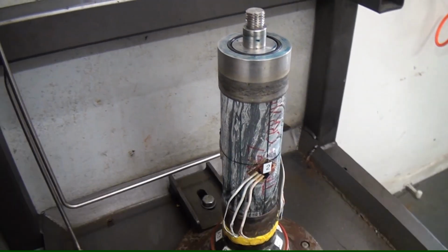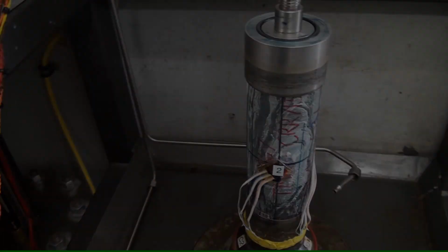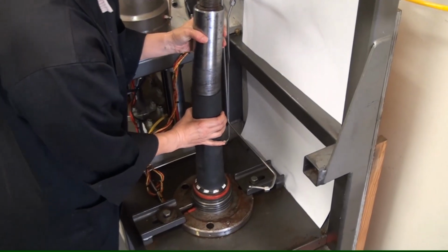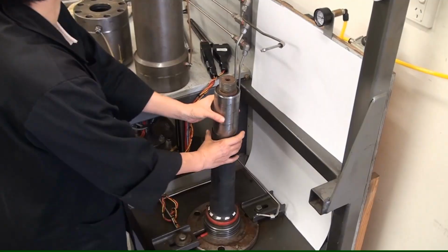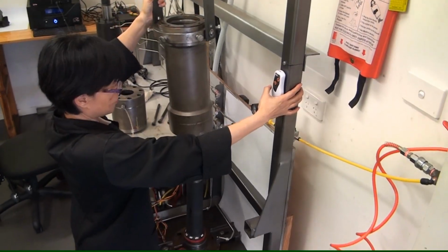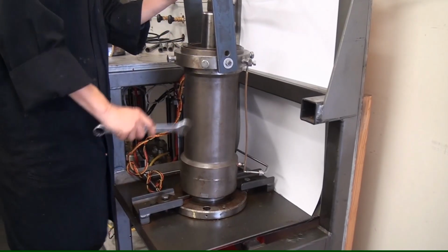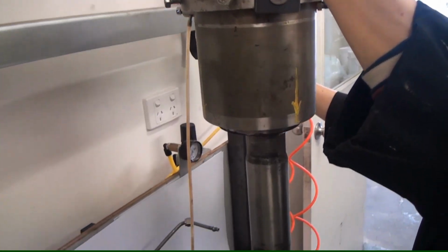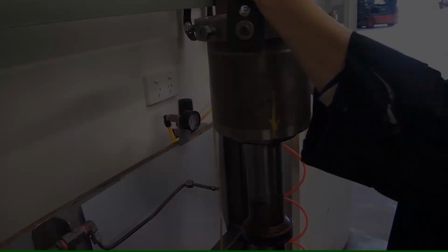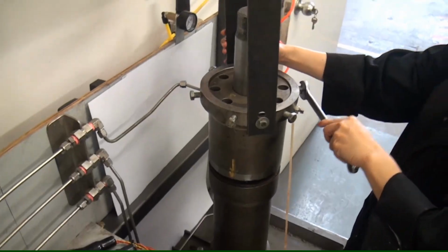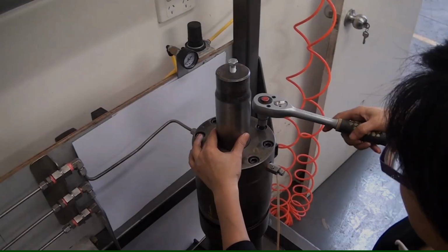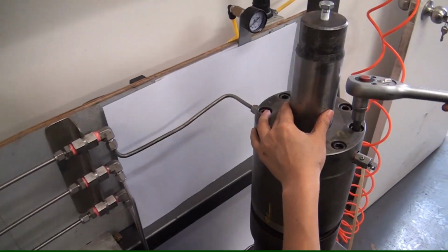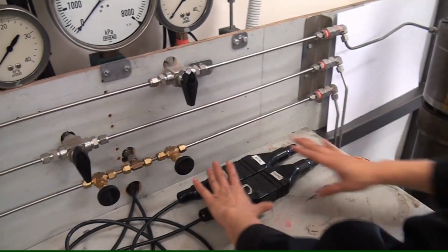SIGRA has developed a triaxial test system to determine the anisotropic and nonlinear properties of rocks. The triaxial test involves fitting a core with strain gauge rosettes, then installing it in a SIGRA triaxial cell. The sample is fitted with a sleeve, which will be loaded hydraulically to provide a confining stress. The rest of the cell is assembled. This includes an internal piston arrangement to provide axial load without an external loading frame. The load sequence is programmed and the test proceeds automatically.